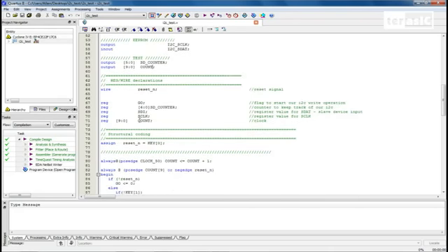Now, our reg and wire declarations. We have our reset, and it's active low, so we have N here. This basically resets all of our systems for the I2C communication. We have our go signal, which is a flag to start our I2C write operation.